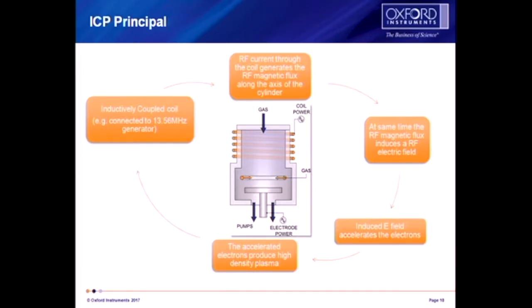So important features on this include a gas ring just above the electrode. This does two things. It's a ring that sits above your wafer and lets the gas in. Because the gas is coming in from all sides, it gives really good uniformity. It also means that your two process gases that come in through the top and the one through the ring don't meet until they're in the bottom half of the chamber. So there's much less deposition on the side walls. When you get a lot of deposition on the side walls, it can build up and you can get flaking. So this increases the length of time you can use your tool between cleans.